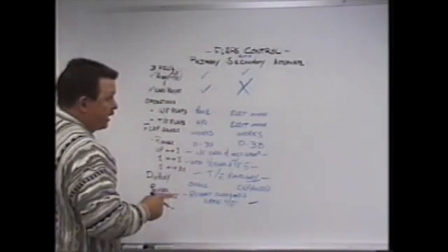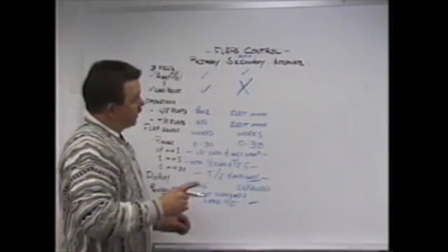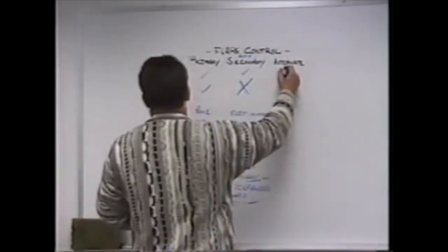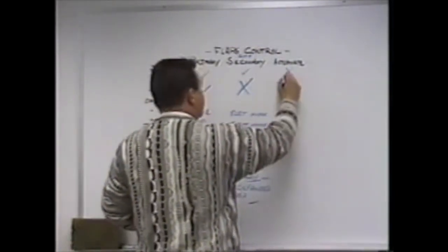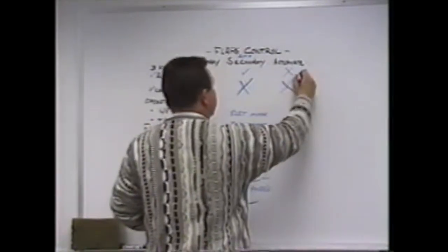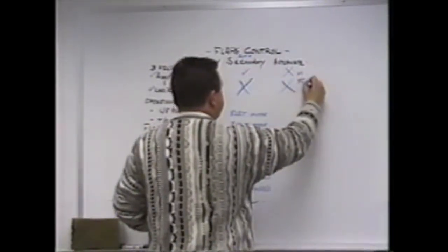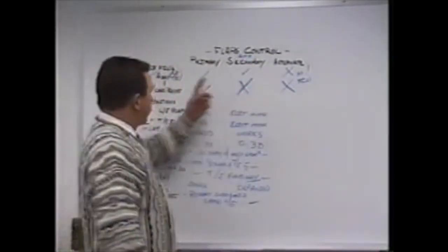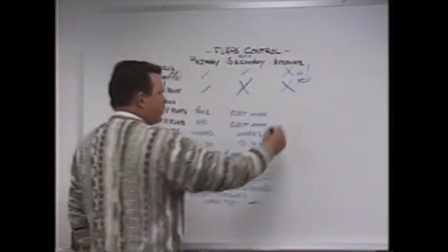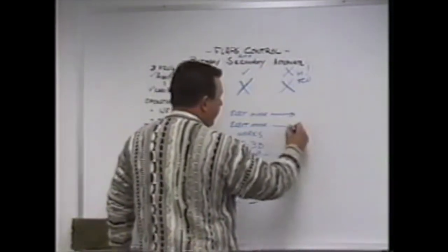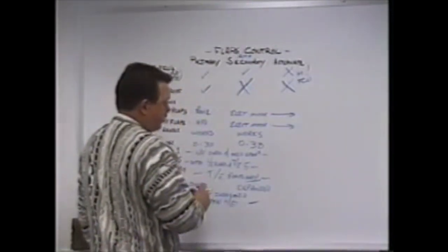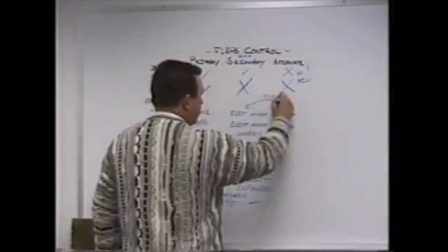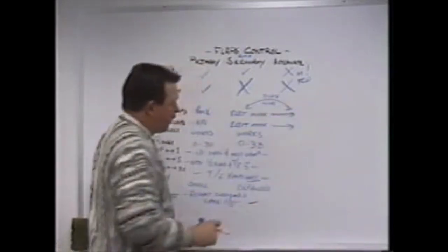Alternate mode, on the other hand, is a different story. When you press the alternate flap arming switch, that will shut off the 3 flap control units. And as a result, you have no asymmetry and no load relief. There are no flap control units. You shut them off. And that protective feature comes from those 3 flap control units. You're still using electric motors to drive out the leading edge and trailing edge flaps. However, it's different wiring. So it's a different control wiring out to the electric motor.